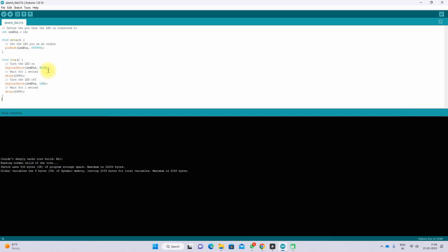Okay, so here you can see that there is no error in the code, right? So for simple LED blinking, it will provide the code, and it does not have any error, right? You can use this code to deploy in the Arduino, and then you can blink the LED, right? So here you can see that the LED pin is taken as default 13, right? So already we know that in Arduino, the 13 pin is connected with the LED.